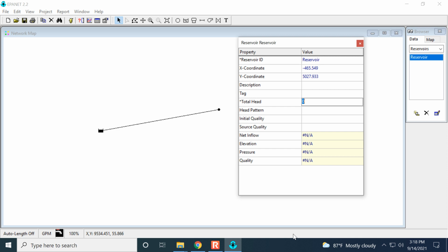Like even if the water level is going down slightly because the reservoir is being drained, the velocity that it's falling is so minuscule that we can effectively neglect the velocity head. And where there's air above the reservoir, where the water at the surface is in contact with the atmosphere, then that means that the pressure is effectively 0. So the head is the same thing as the elevation.